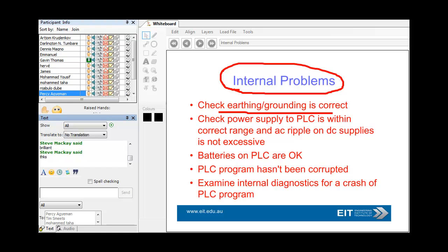Yeah, mainly with communication links, so we don't use a lot of analogs, but we have lots of problems in high voltage substations with circulating earths or that type of thing.